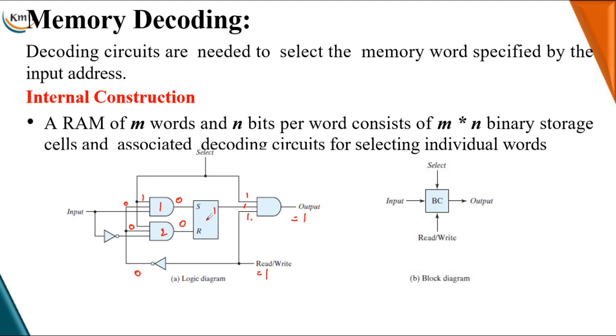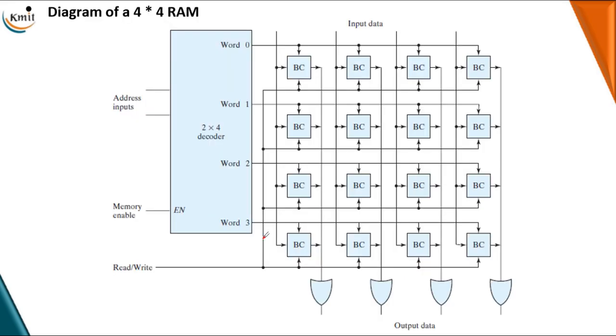If you had stored a 0 data input earlier, that 0 would be transferred as one of the inputs of your third AND gate, so at your output gate you would have a 0 output. Like this, data is loaded or retrieved from each binary cell by selecting it, enabling a control input, and supplying a data input of 1 or 0. So you can obtain your output from each binary cell. But in order to decode all of these, we need to go for memory decoding.